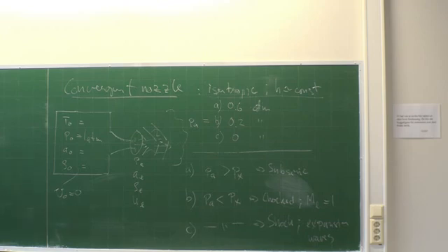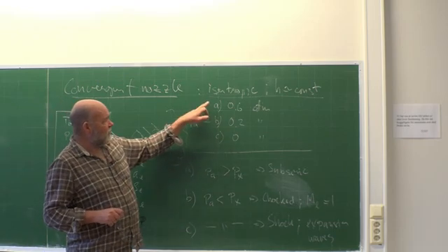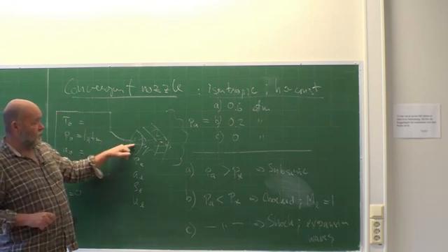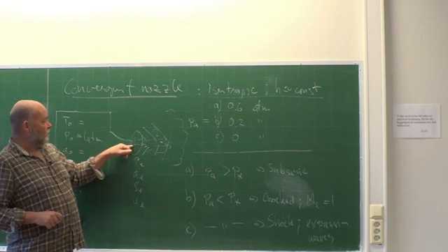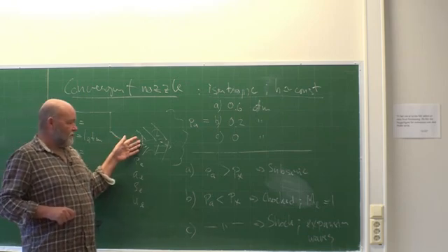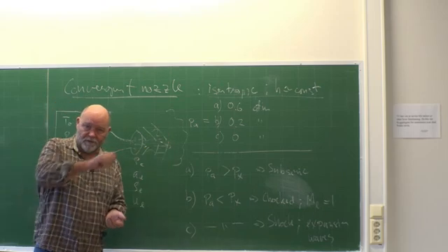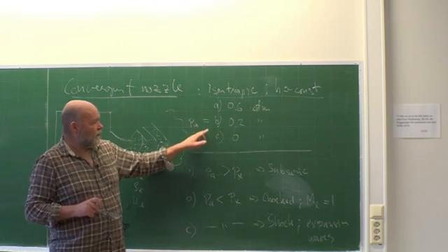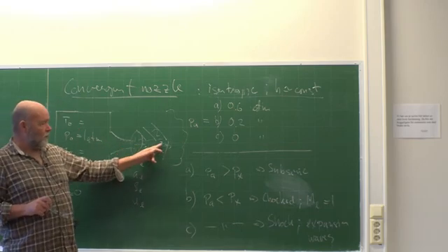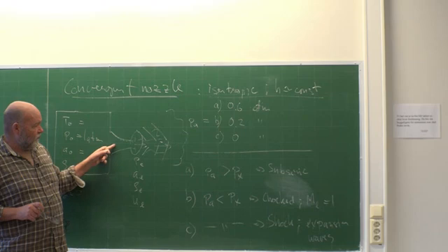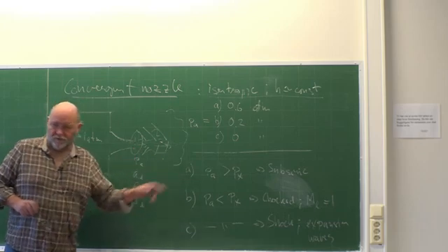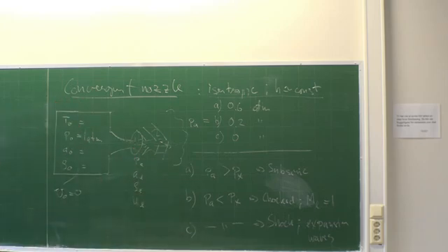But I sort of wanted to check out that you can match no shock, then the velocity will accelerate through the convergent part, and then it will decelerate through the divergent part, of course. But when you come to these two, then something strange is going to happen. The velocity will increase here, of course, continuity, but then the velocity is going to increase even when the area gets bigger and bigger. That's where we have the shocks.